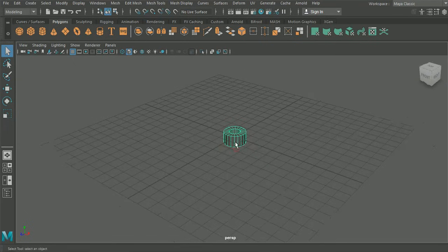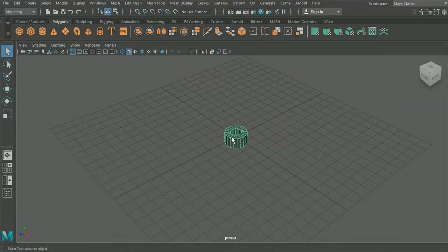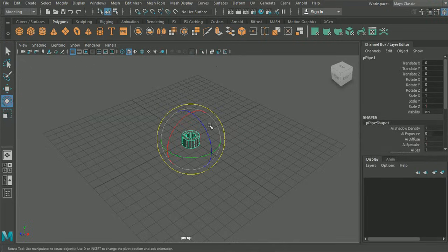So what we want to do here is essentially position this tube on our front arch, and edit the different subdivisions that we have along here in order to match the model that we've got before we actually start deleting any faces from there. First things first, we're going to need to rotate this so that we can use the actual edge. It doesn't matter if it's negative 90 degrees or 90 degrees, either way we're going to have a nice face sitting there ready to go.